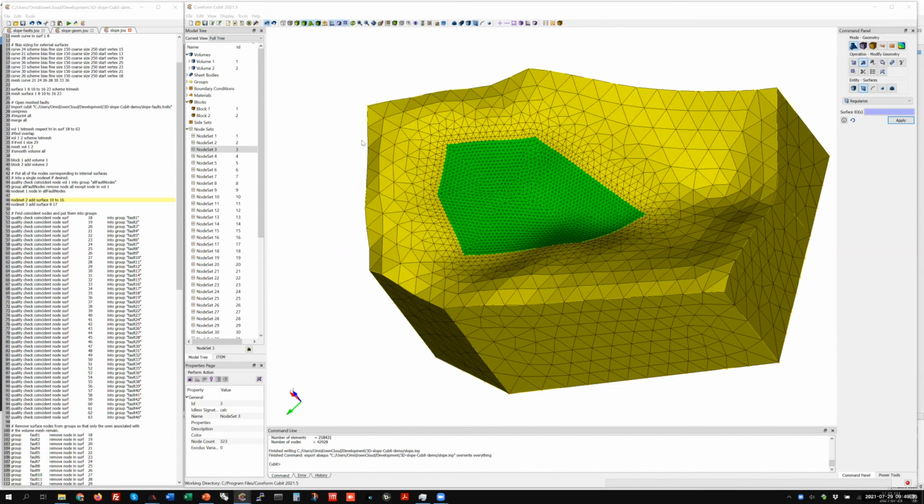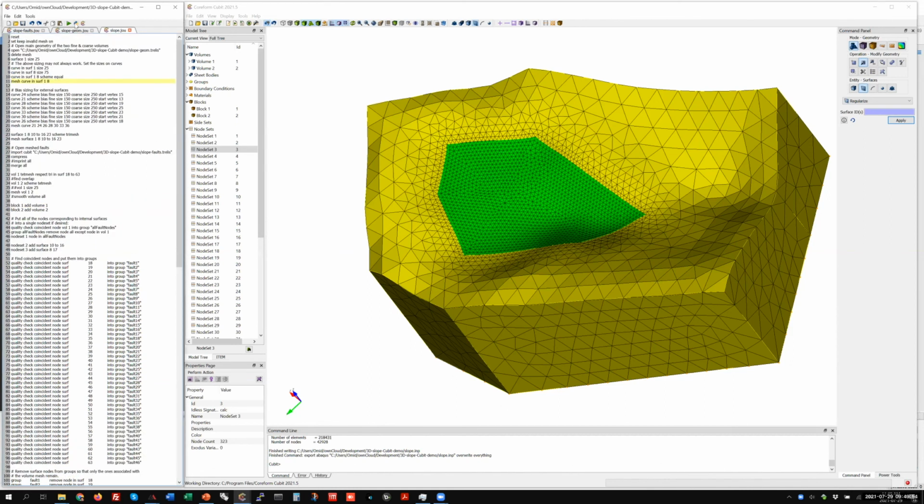And as you mentioned, I generally use the journal file, but if things get a little bit more complex and I need to do things a little bit more programmatically, I will just use Python within Cubit. So you could very easily translate all of your commands that you have here into Python. It just wraps it around. And then you could use generic Python code as well. There are cases where I had to draw something repetitively, so I'll draw it once and then repeat it with Python.